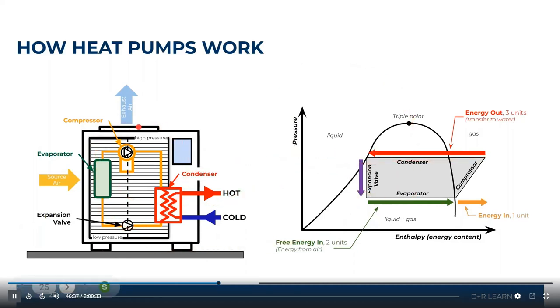But in our air-to-air heat pumps, you're going to have a low pressure, low temperature vapor that's going to be transferred from your outdoor coil, which is typically your evaporator in a heat pump system. And that refrigerant is going to go through your reversing valve or a metering device. I'll tell you what we'll do. We'll talk about the heat pump system first, because I always get these two a little bit confused when we talk about AC, just due to the reversing valve. We'll keep it strictly heat pump right now, and then I'll talk about the AC cycle with heat pump.